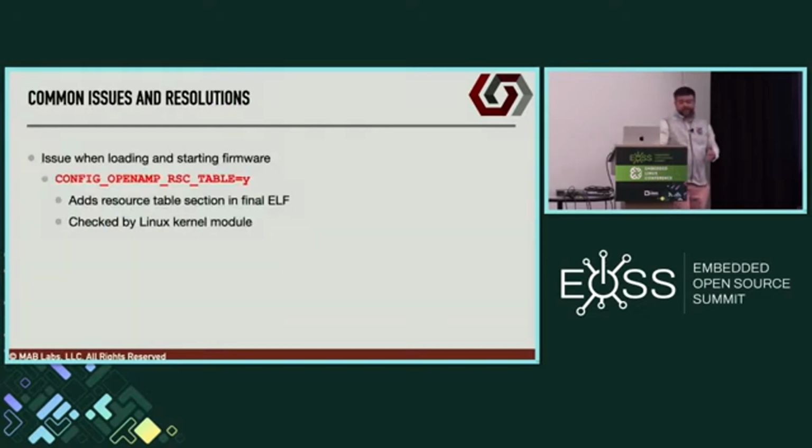So, pivoting into some of the common issues that I encountered, I can share some of the lessons learned with you. One of the first things that usually happened is issues in loading and starting the firmware. For the kernel module itself, if you don't have the appropriate entries in your ELF file, it's going to throw an error. And one of the biggest reasons was you need to actually define this config option,